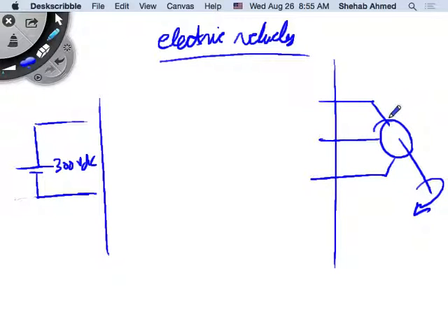Haytham's class, in 338 course, you've studied synchronous machines. So it's either a permanent magnet type synchronous machine or an induction machine, okay? Typically a permanent magnet synchronous machine is more common nowadays. At least the Prius uses a permanent magnet synchronous machine. The Honda uses a permanent magnet synchronous machine. The Tesla uses a permanent magnet synchronous machine. So all of these use permanent magnet synchronous type machines. So three-phase permanent magnet synchronous machine, some AC voltage that's high, comparable to 300 volts.